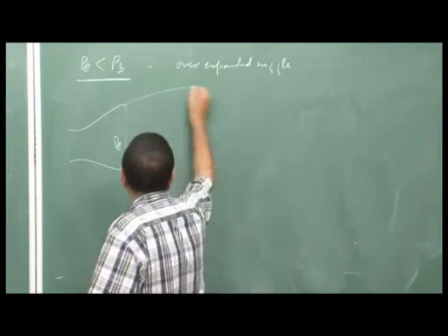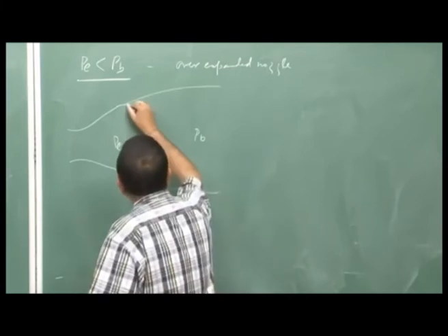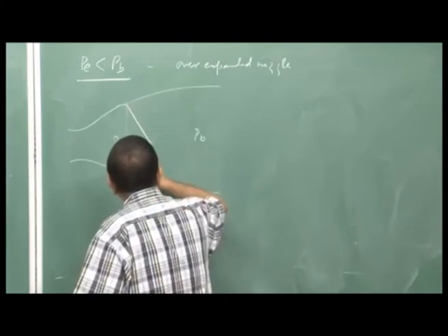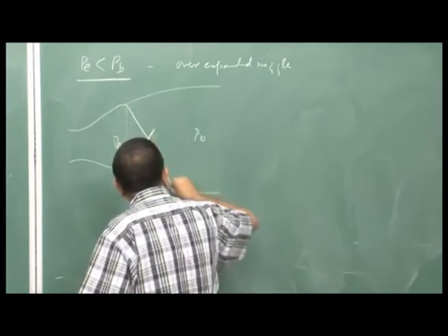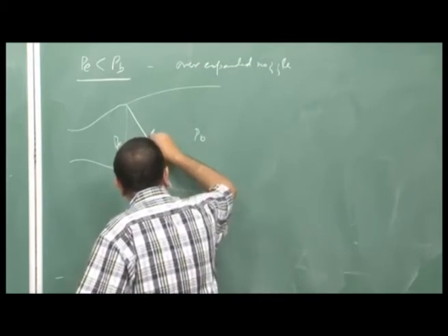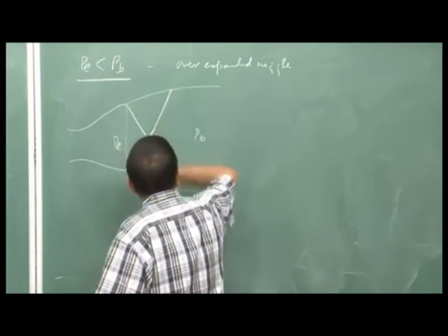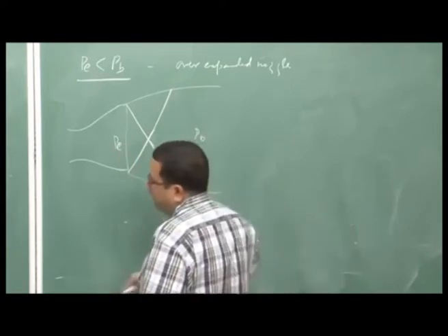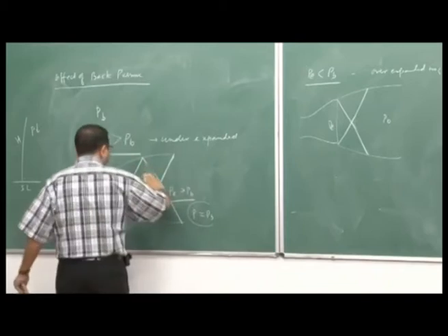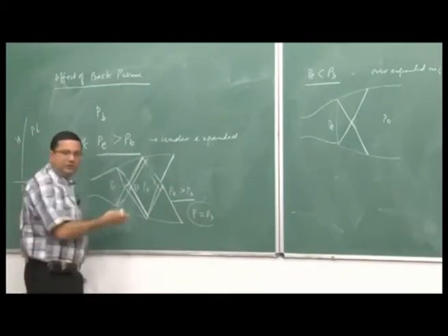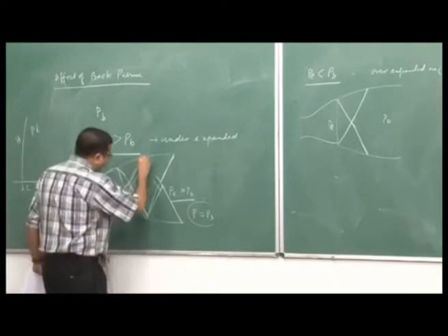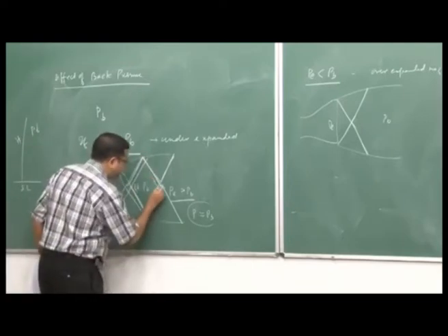So, again this is my boundary. First there will be an oblique shock wave emitting from here. When they cross, it goes like this, you get a lambda shock. Actually here, sorry, there is a mistake. It continues as an expansion fan, two expansion fans crossing each other. From here it reflects as a shock wave.